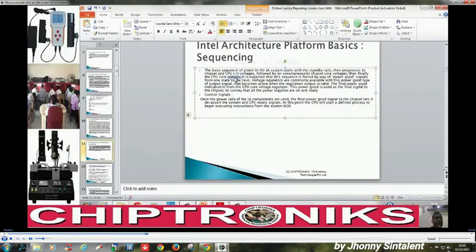One thing we must note and understand is that everything in the notebook motherboard, we are talking in respect to the chipset, PCH. Everything starts from PCH and everything ends at PCH. That is, everything basically starts from PCH and ends at CPU, but the entire power sequence is governed by PCH or ICH that we are talking about from the very first class.